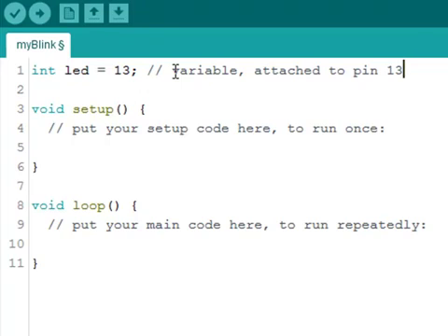So we can run this sketch, which is an Arduino program, without actually having created anything on our breadboard in terms of a simple circuit or anything like that. Now in setup, because computers are dumb, we do need to tell them, is this LED an input device or an output device? Obviously output's light, so we type pinMode, LED, comma, OUTPUT. Noticing the output is in capitals, and then we finish that line with the end of line terminator, which is a semicolon.